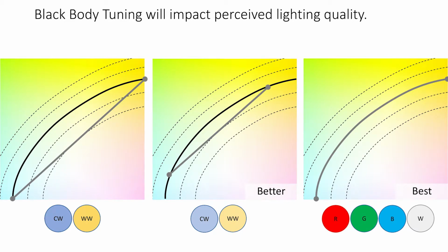So the whole point of what I just showed you was to talk about this slide. If I'd chosen in this fixture 2 LED strips that were very, very far apart in color temperature, say, I'm just going to make this up, a 10,000 Kelvin strip and a 2,000 Kelvin strip, the only place I can go is a straight line between those two things.